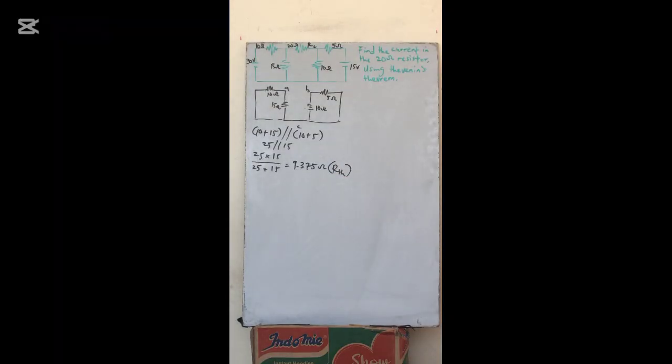Now we've gotten our Thevenin resistance, and remember we also need the Thevenin voltage. So what are we doing from there? To get the Thevenin voltage, we are going to look for this place here, VAB. Let me just say, this is the bridge between this side and this side. And I told you, anywhere that we open circuit, we serve as our V Thevenin. That's what we did last time. So this place is the V Thevenin that we are looking for. So V Thevenin equals VAB.